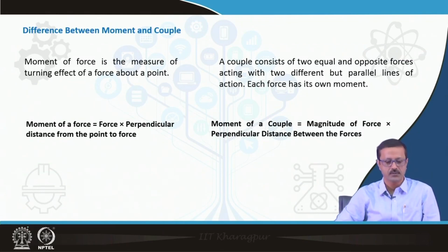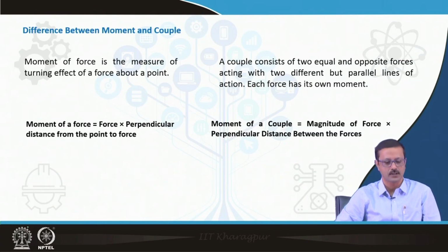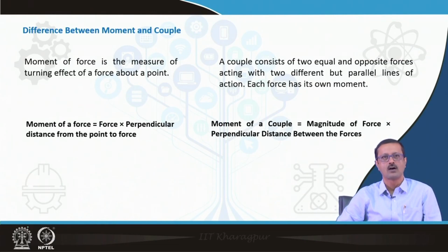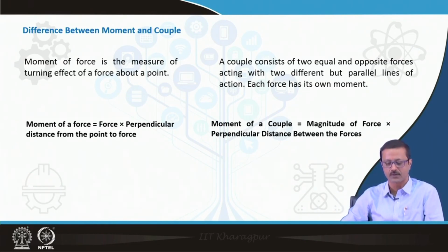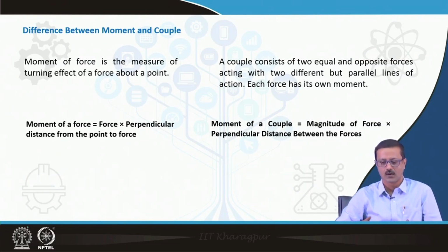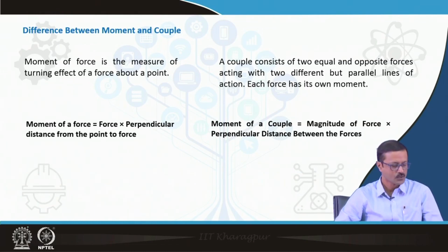Now, what is the difference between moment and couple? Already I have discussed that the moment measures the turning effort, or the rotational effort, by a force about a given point. Couples are two equal and opposite forces acting on a rigid body along parallel lines. Non-parallel forces may not give you a couple; you may have to resolve them and find the couples. So, this is the difference between the moment and the couple.